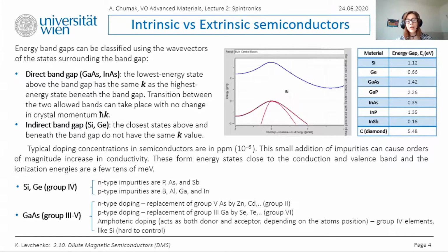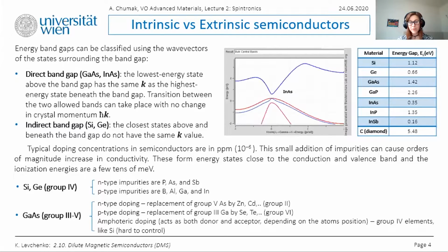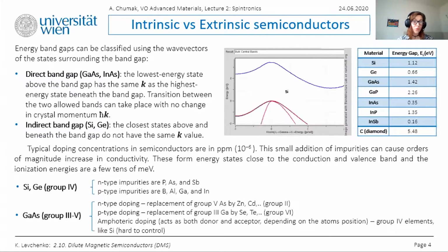So when we pop a pentavalent element into the lattice, we are doping the silicon with phosphorus, for example. This pentavalent element has 5 electrons, so it shares an electron with each of the 4 neighboring silicon atoms. Hence, 4 electrons are tied up with the silicon atoms in the lattice. This leaves an extra electron, and this excess electron is free to move and is responsible for the conduction, hence the N-type.